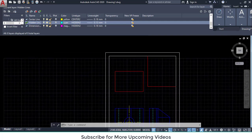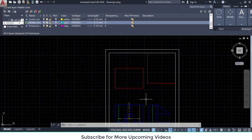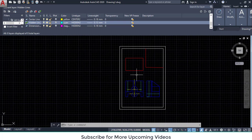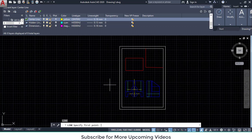Finally, I draw top view here. So first extend this center line here. So select center from the layer and with the help of line command extend this center line.